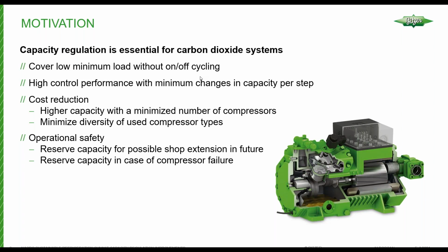assistance in achieving these goals of reducing compressor cycling, minimizing capacity gaps, possibly cost reduction by eliminating other components or reducing the number of compressors on a rack, and mostly providing flexibility of having a second option, a second layer to what they have had in the past for capacity regulation on CO2 compressors. So this was the big driving force by BITZER R&D to come up with this solution for our customers.